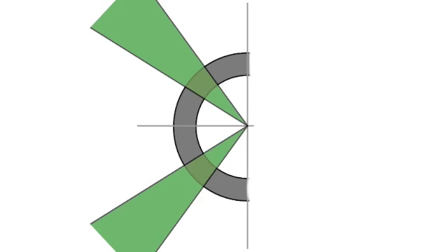So if we also take a nice graph here, this was the previous finding between 2.9 and 4.2, and now we have another constraint. So this is 36 degrees for the second line, 58 degrees. So the intersection of these two constraints, the natural frequency constraint and the damping ratio constraint, we now know that we can only take the values in this region. We can only take the intersection of these two criteria. So these are the parameters that would give us the design specifications of the question that we are dealing with.